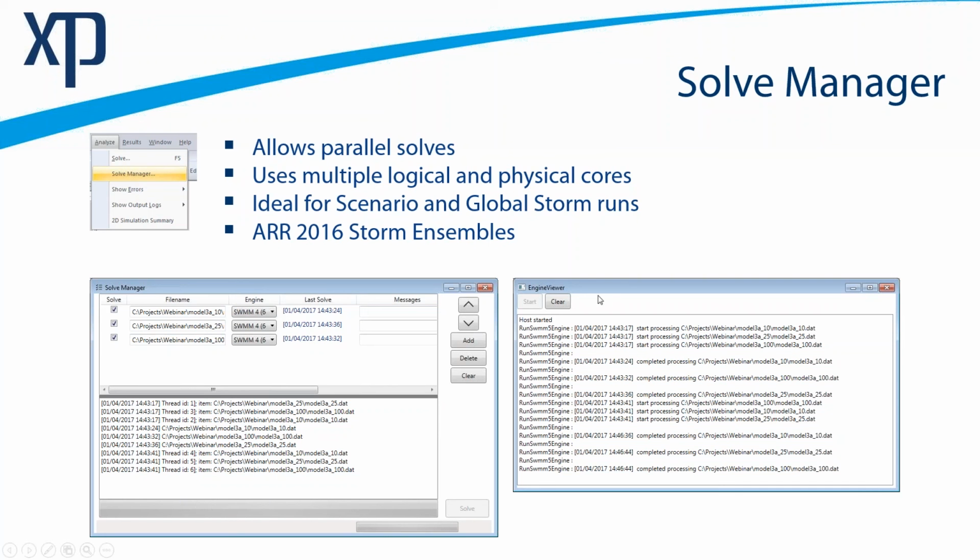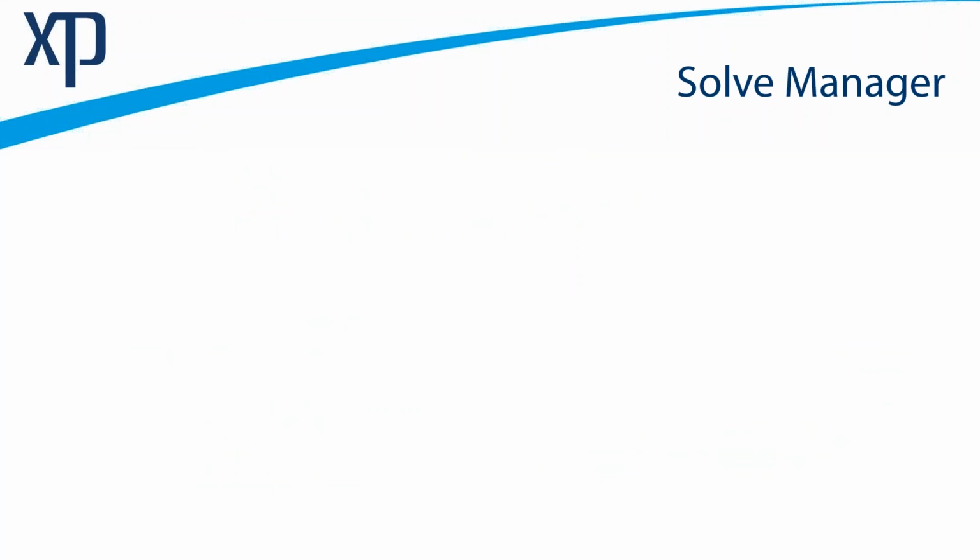Both dialogues are required, so we've had a couple of instances where people have closed their engine viewer and then the Solve Manager won't run. So if you don't like the position of where that dialogue is located, move it off to the side or minimize it. Don't delete it. It looks like we're going to have to prevent people from closing this dialogue without closing this one in the future, maybe in Solve Manager 2.0. Just a little bit of wisdom there that I'm imparting to you.